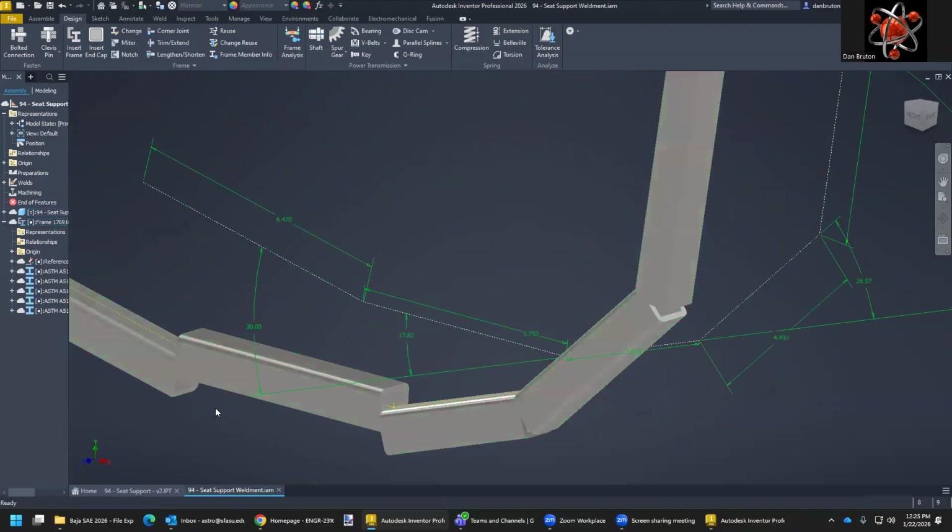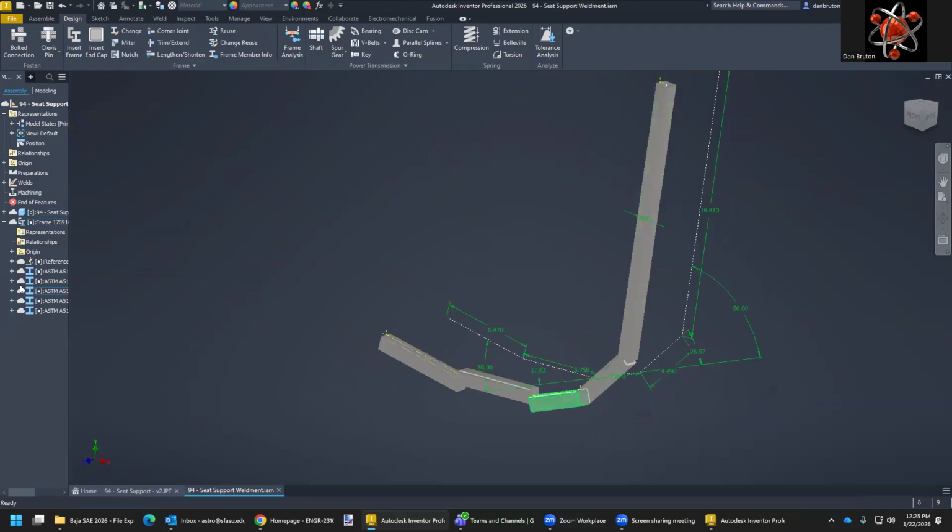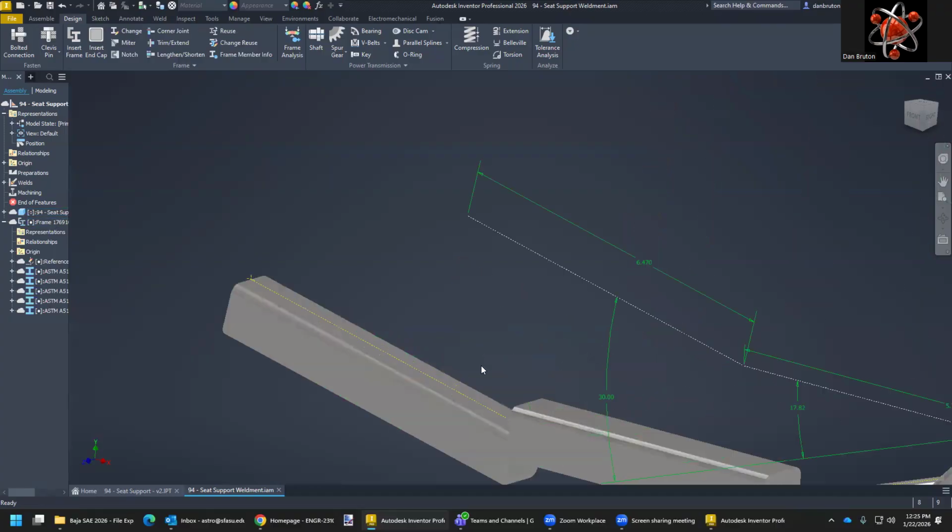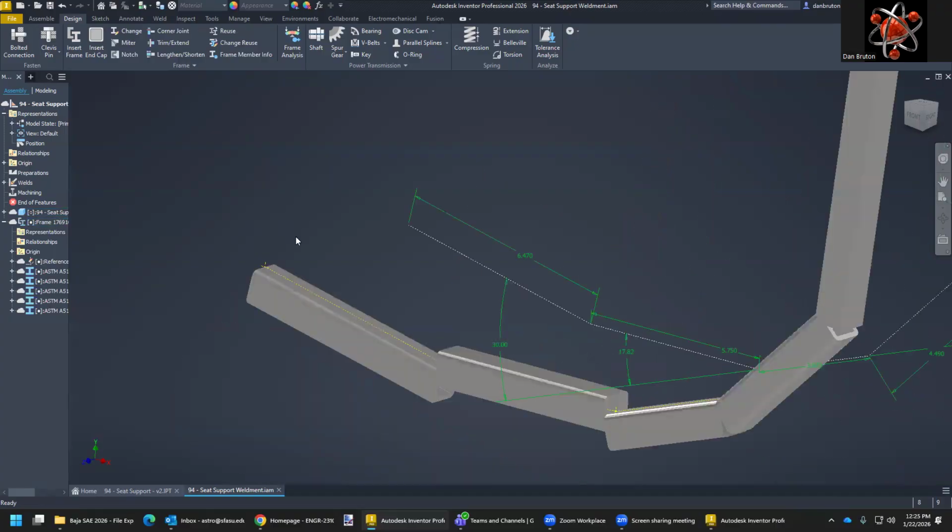This one was not the center going through it. So let's edit the weldment to see if that could work. Maybe just hit Control Z and go back to make sure it goes along that line, because here it was midpoint, there it was edge. That's not the way it should work.